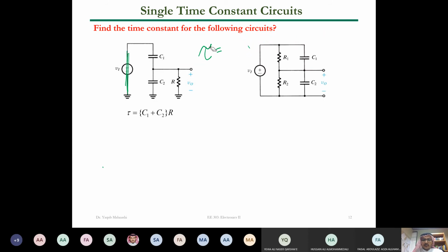What is the time constant seen by this circuit? Or what is the pole for this circuit? What is the condition we have first, guys? Deactivate the source. Deactivate, exactly. So this one will be connected to ground. Will be shorted. R1 and R2 in parallel. Exactly. So the time constant will be, do we have 2 different capacitors, or is C1 going to be in parallel with C2? Parallel. In parallel.